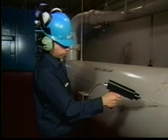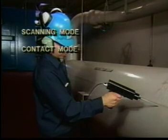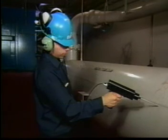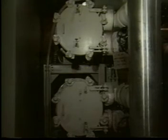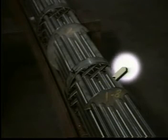The leak detection methods we will use include general scanning mode procedures using the contact probe, pressure, vacuum, and tone methods. In an online environment with equipment under pressure or in a vacuum condition, a leak will move from the high pressure side to the low pressure side, generating a turbulent flow with strong ultrasonic components. These sounds are detected with the Ultraprobe using the scanning or contact mode.